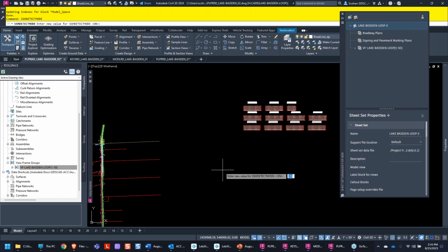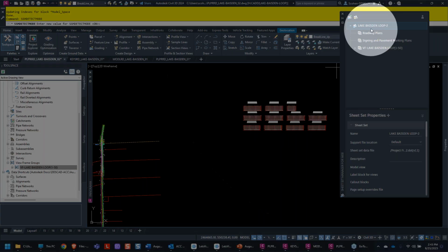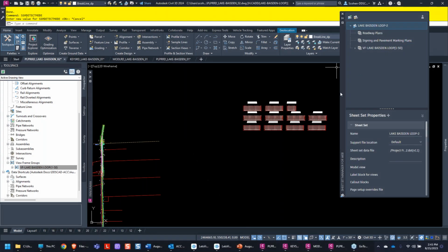And the problem with that is, if you set it to off, the reason I'm showing you that is sometimes the synchronization that you should be able to get from editing properties doesn't happen. It just doesn't. I don't know what it is. Obviously they're going to work on it, I'm sure. So what you want to do is set it to off, open up your sheetset file and do some stuff there, and then it updates your layouts, it updates the sheets and so on. Okay, so just be aware there is some stuff that is still happening.